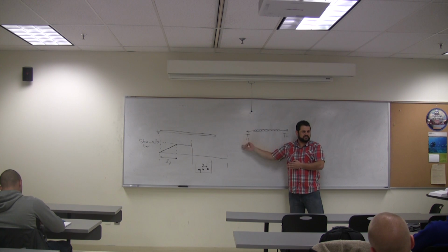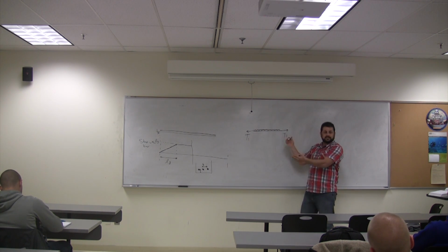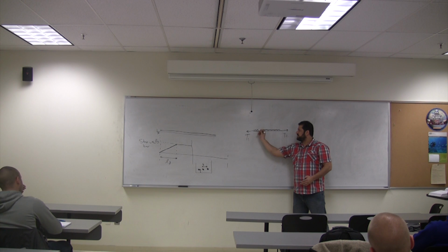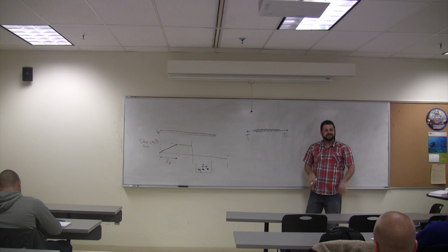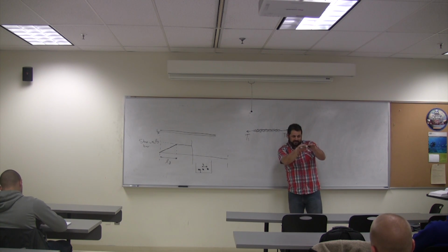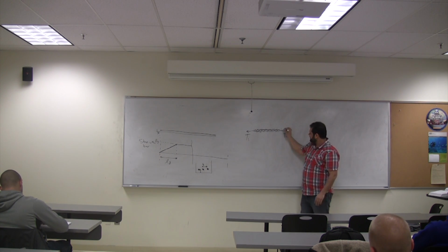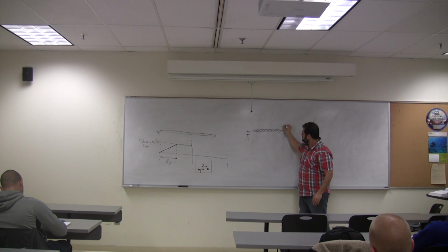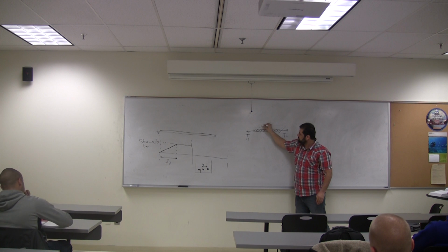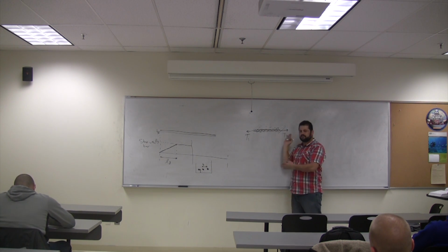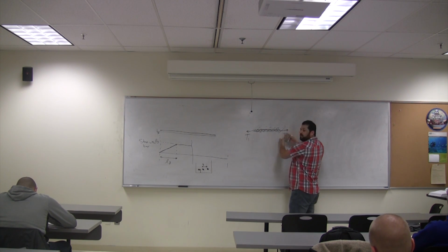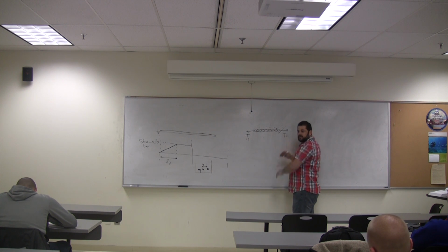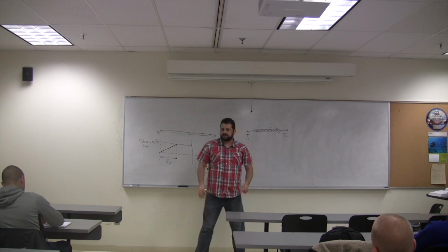Usually we have here, if this is close to the support, this is 0. So for this balance, you need to have something coming from friction. Bond stresses, some kind of a shear. Over what? Over the width. Over this area. That's the concept of development length. This must be enough length here so that the bar can develop its intended stress at this location, or its full capacity.